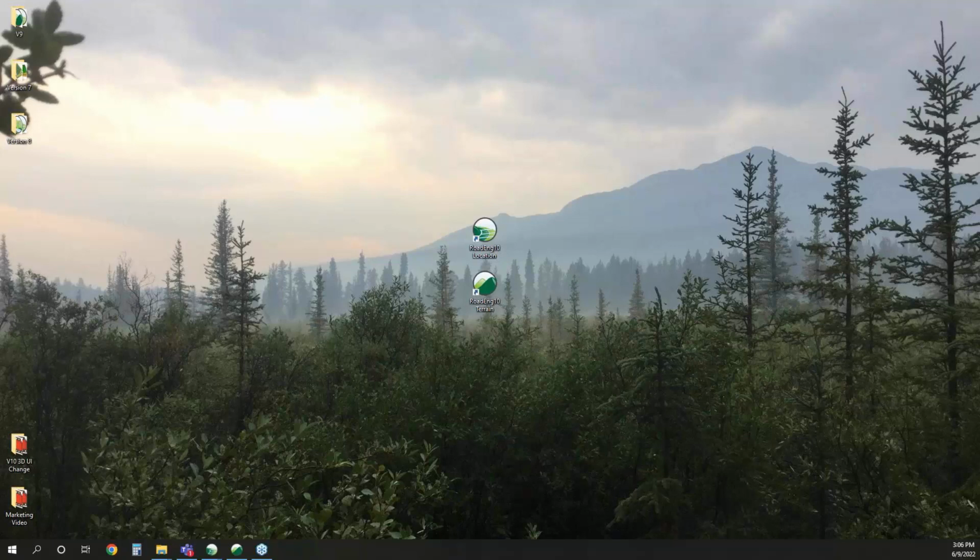So one thing you'll notice when you open the software is that when you install RoadEng, you get 2 modules. So we're going to start out in the terrain module, which is this guy here. We're going to build our tin, so our triangular irregular network to represent our ground. And then we're going to jump over to location, and we're actually going to design our alignment.